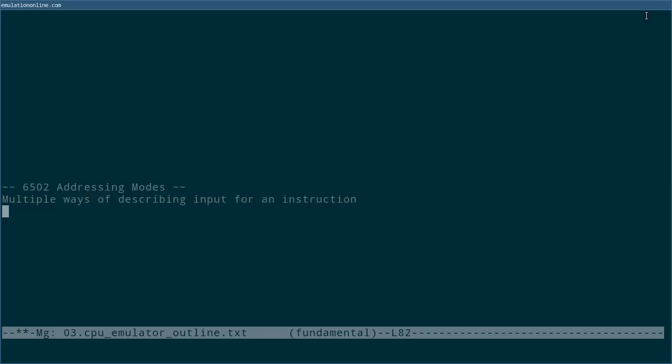The first addressing mode we'll look at is immediate. Here, the value is encoded directly after the opcode and refers to the exact value of that byte. We actually saw this with the LDA example earlier. The pound sign signifies that this is an immediate. And when we look at the assembled machine code, we can see that the 20 is directly copied after the opcode. What if we remove the pound sign?